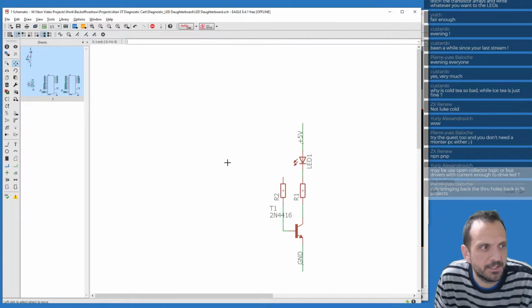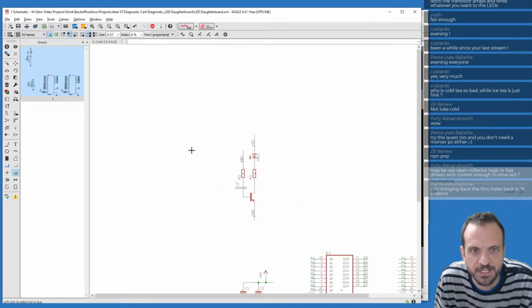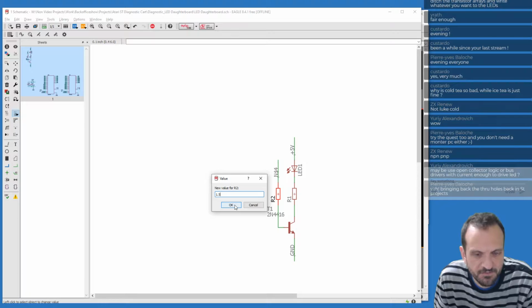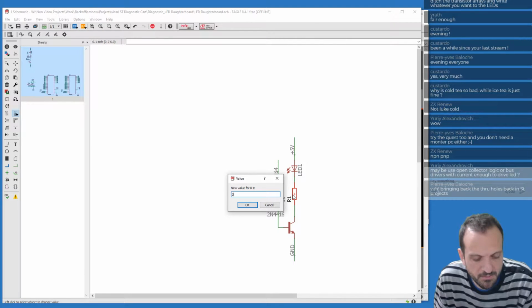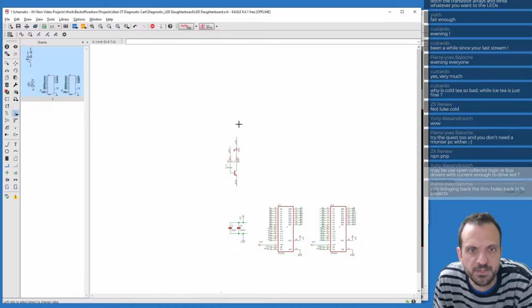So we're going to pop that in like that. Do you see it there? Yeah, I think we need through hole on ST projects, don't we? Absolutely, I agree. And we're going to pop that there like so. Boom. And that's going to be the address there. I'm going to leave it like that. So you can actually put values, by the way. We haven't assigned any value, but I'm going to put nominally at the minute like 1.5k maybe, or 1k. That would be all right. And then maybe 330 ohms for that guy. And I think the rest is okay.